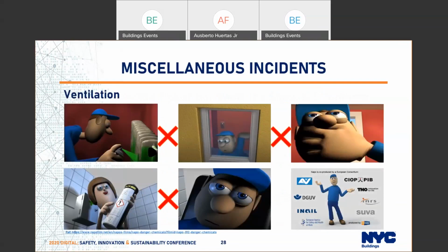Ventilation is not only important for carbon monoxide, but it's equally important for other gases and fumes. This is another scenario where it is important to ensure proper ventilation when working in an enclosed area. If ventilation is not possible, appropriate PPE should be used. Examples are a dust mask for concrete demolition, a P100 for gases and fumes, and a self-contained breathing apparatus with medical approval for other hazardous areas.